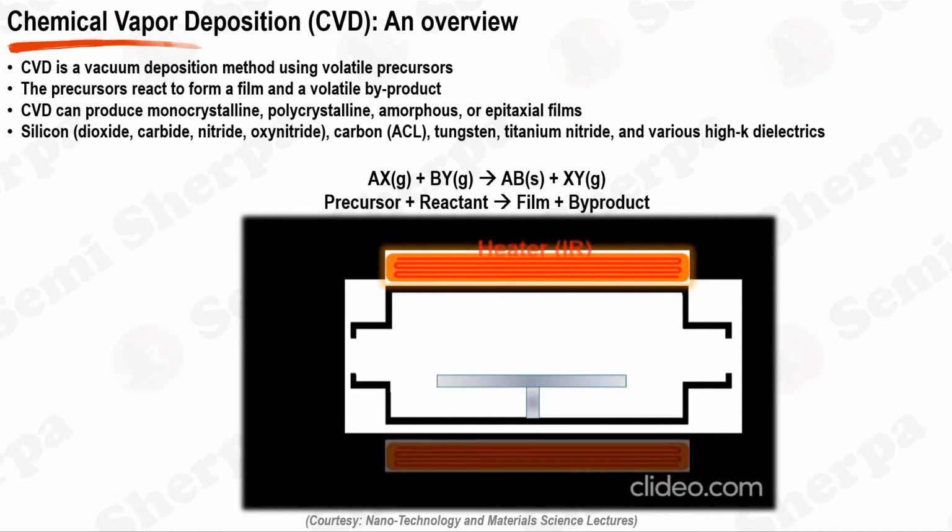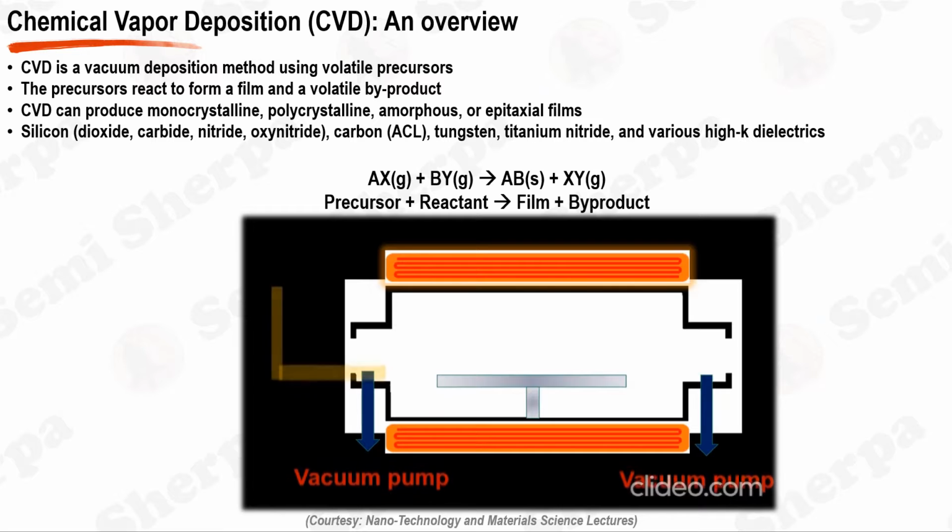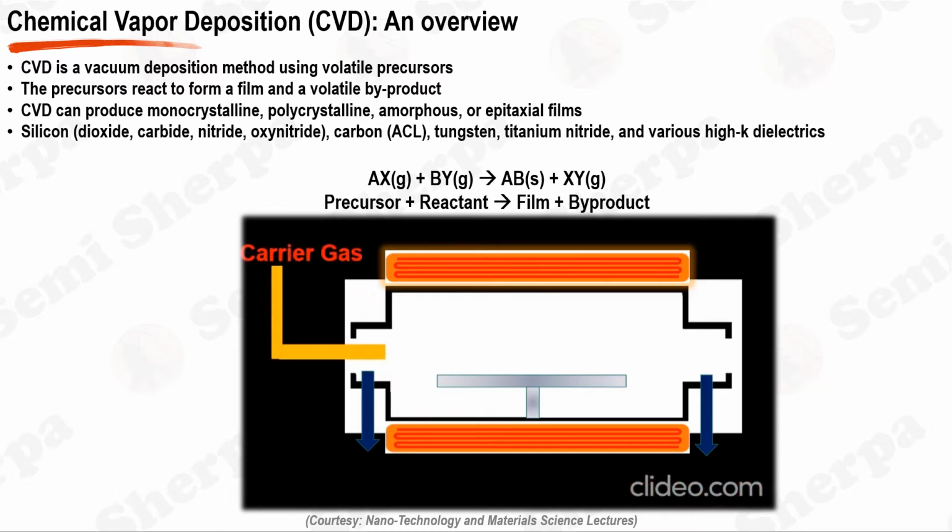Inside the chamber, the substrate onto which the film is deposited is placed on a holder, also known as a susceptor. This holder can rotate or move in other ways to ensure even film deposition across the substrate's entire surface. Additionally, heaters are incorporated into the chamber to provide the necessary thermal energy for the chemical reactions to occur. These heaters can be direct contact types or indirect types like radiant heaters. For some CVD processes, the heaters can reach temperatures of up to 1000 degrees Celsius or higher. Precise temperature control is vital for achieving the desired film characteristics, as it can influence the reaction rate, film uniformity, and film composition.